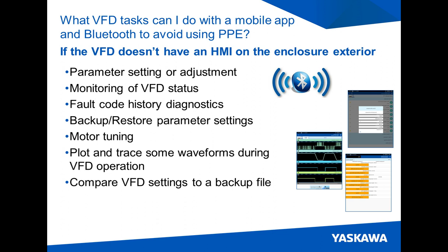And this assumes the manufacturer provides this mobile app with these features, and your experience with different manufacturers' mobile apps can vary between manufacturers. You can do parameter settings, adjustments, monitoring, fault code history, backup and store the parameters, motor tuning. You typically don't see this on an HMI display where you can plot and trace various waveforms and things going on with the VFD.